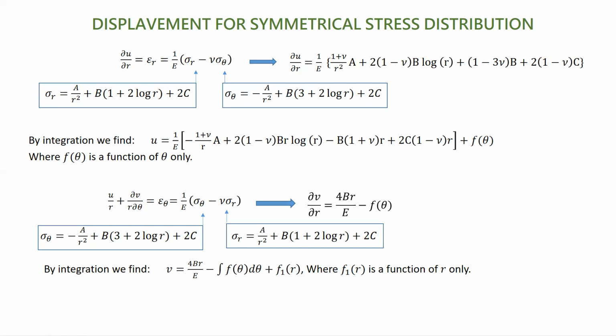And I'm not just looking into that beam with the bending moment we applied. I am trying to get the displacement in a general case, for any problem with axisymmetry, not only limited to pressure vessels, cylindrical pressure vessels, or the case of the curved beam with the moment at the ends. So these are the general equations, sigma theta and sigma r. Let us substitute the values there and correlate the strain to the stress accordingly due to Hooke's law.